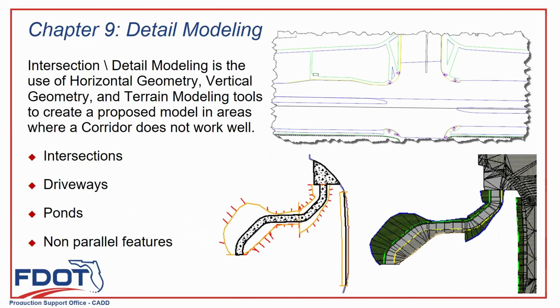Yeah, and some people may just think, oh, we're doing this for cross sections. No, it's more than that. We're doing it for automated machine guidance, so we can actually deliver the 3D model. So that's what we should be doing. Anytime we create the 3D model, we should also deliver it. I know in practice it's been only occasionally, but if you need cross sections on a roadway, you're creating a 3D model. So do it right and also deliver it.